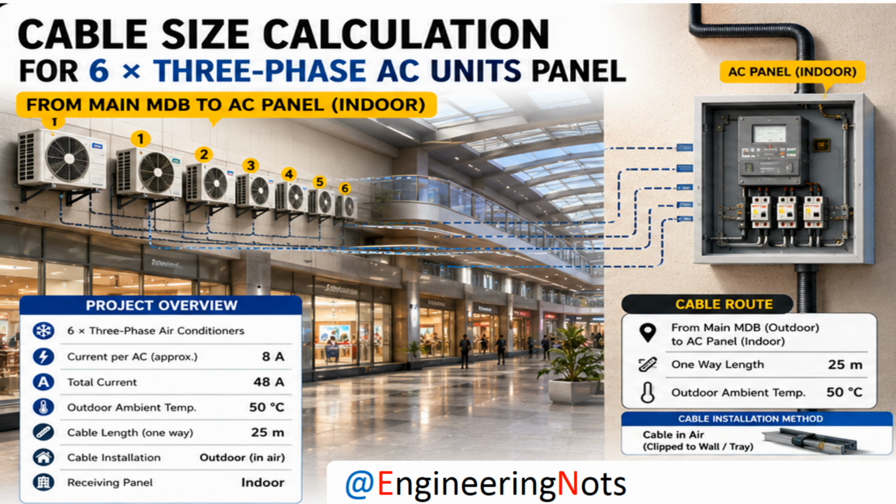For example, under IEC 60364 guidance, the correction factor at 50 degrees Celsius depends on the cable insulation. For a PVC cable, the factor is lower than 1, which means the cable's allowable current is reduced at this high ambient temperature. And this is exactly where many cable sizing calculations go wrong.